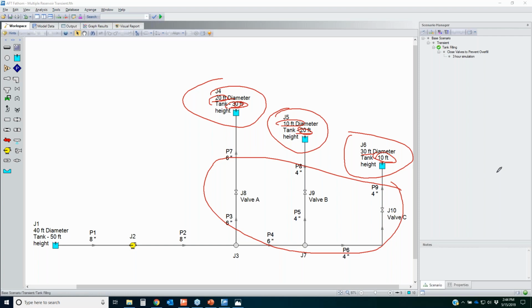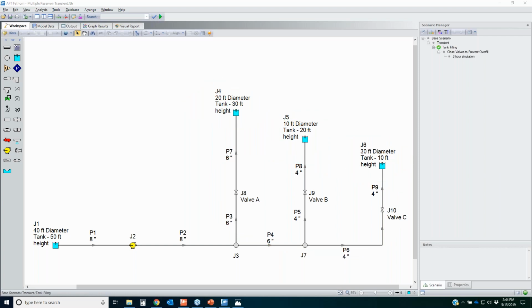The reason why I wanted to demonstrate this example in the previous webinar and then bring it back today is because this is one of these classic fluids problems, which is really complicated to solve by hand calculation or by spreadsheet. And one of the things that are really important that people care about is a pump and system curve. A pump and system curve is really easy to generate right in Fathom, but there are many times where a pump and system curve is just not even useful at all.